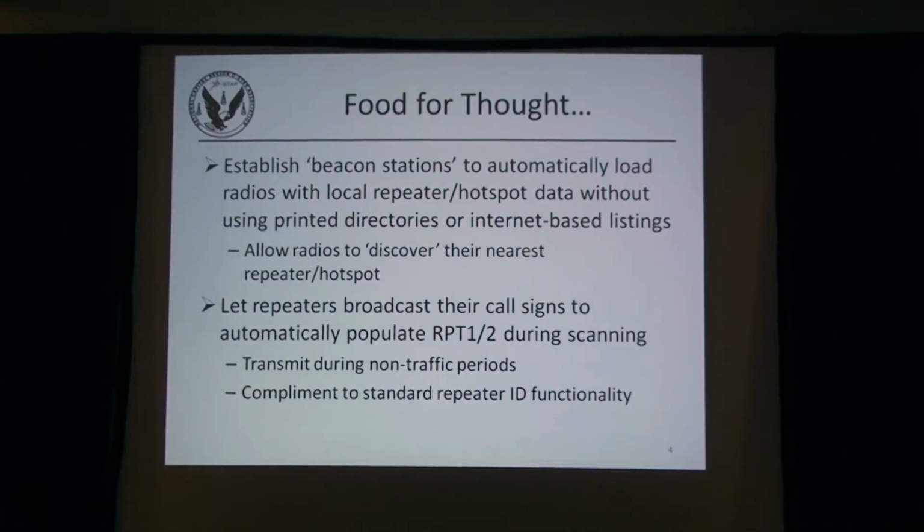One of the other thoughts that I had would be a better way, and this kind of ties in with what Bob has been saying here with APRS, that you can actually have the information show up as far as what repeaters are available, how far away you are from something. In D-Star, you don't have that. Basically, you have to know where your repeaters are. You've got to go to an ARRL repeater directory or some other local directory. And it's just like programming any other radio. You got to go in and put in the frequency, the call sign, the offset. You don't know where you are.